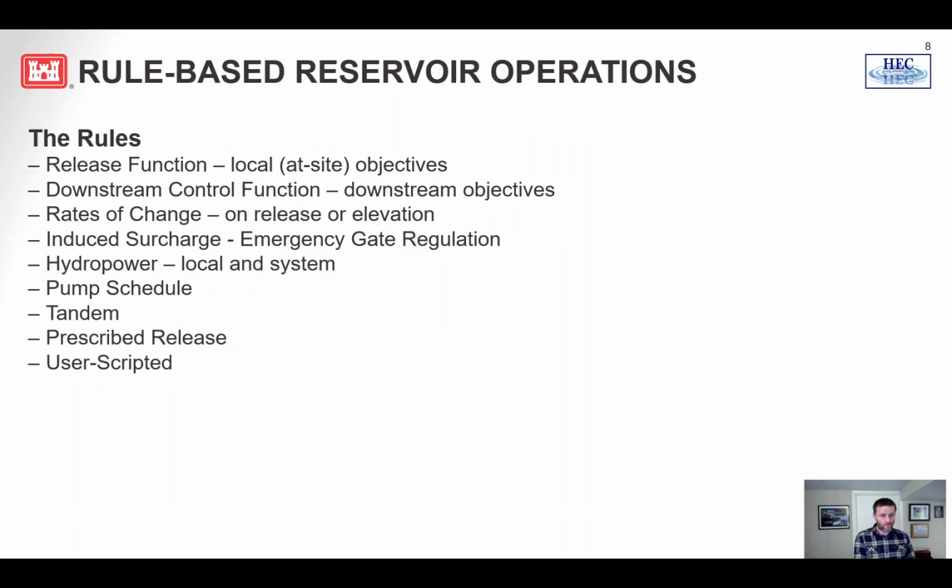So if you have one reservoir upstream that has to balance the needs of downstream reservoirs, you can do a tandem operation. There's also system operations too. So not just tandem, but it can also be a system where there are parallel systems of reservoirs operating for a common downstream control point, and they can also be in tandem. So it's pretty complicated when you start adding systems.